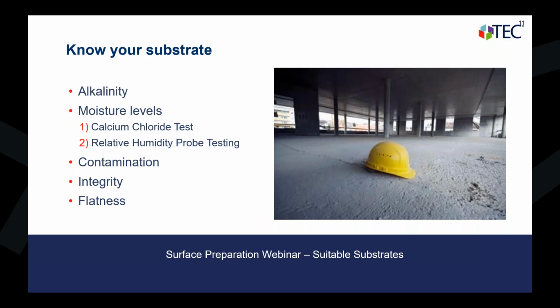And again, knowing your substrate, we want to make sure we're checking moisture levels. High moisture levels can create problems with bonding. If you have hydrostatic pressure, obviously we don't want to install in that. In doing those moisture testings, you can do a calcium chloride test or the RH test.